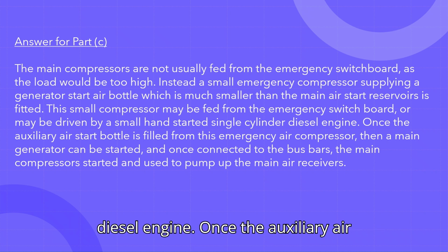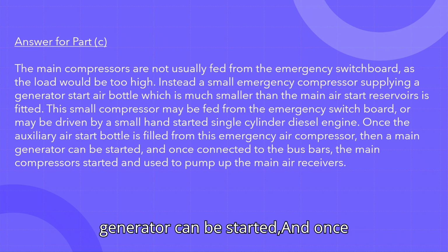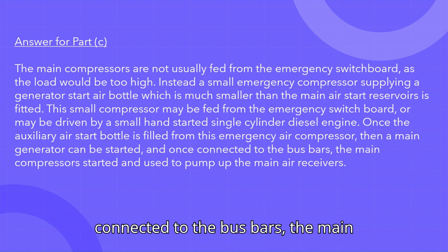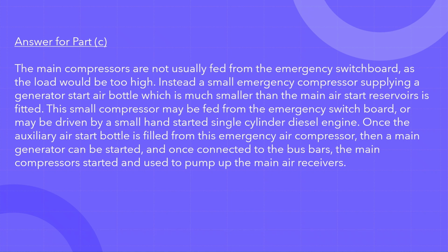hand-started single-cylinder diesel engine. Once the auxiliary air start bottle is filled from this emergency air compressor, then a main generator can be started, and once connected to the bus bars, the main compressor is started and used to pump up the main air receivers.